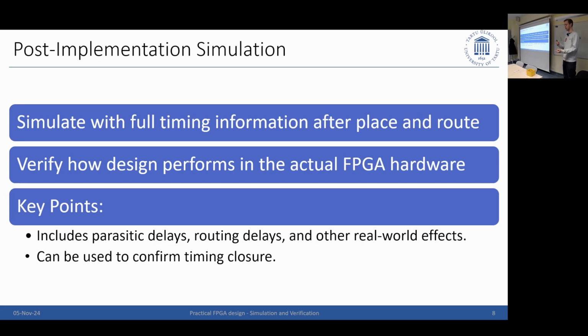So you get much faster results from behavioral simulation and a timing report. If these two work out, and we have not covered the timing reports yet, but we will in the lecture after, there you will see if you have a delay which is a problem on any signals. The simulation is just on top of that, doing the same and showing you if you actually get the same result, if you have missed anything. So this is not going to be run very often. For our designs, I do not intend that it takes a day.